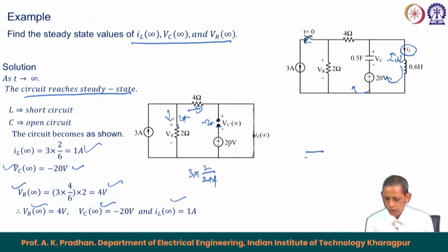Similarly, if you see this capacitor, if the capacitor is charged with, let us say, V_0 with this plus minus, then when it is connected to a resistor R, the capacitor current earlier was flowing in this direction to charge it, but now the capacitor, like a battery, will circulate current through this one. So, the current direction in the capacitor will change, but the voltage of the capacitor will not change, because this plus minus will be maintained throughout. Yes, the capacitor voltage goes on decreasing till the energy is exhausted. So, these are the basic things which we should remember while solving different circuits.